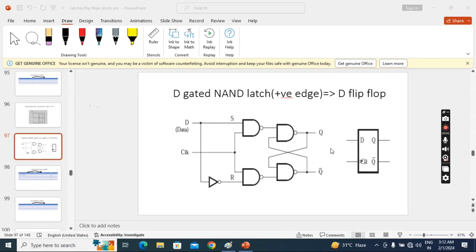In this lecture, we'll discuss the necessity of D flip flop. You know, we get D flip flop from SR only by interconnecting JK and connecting one inverter at a suitable place. So this D flip flop was ultimately developed for the implementation of shift registers. In shift registers, the input and output data should be the same. In that case, only D flip flop is suitable. No other flip flop will produce the same output as input.